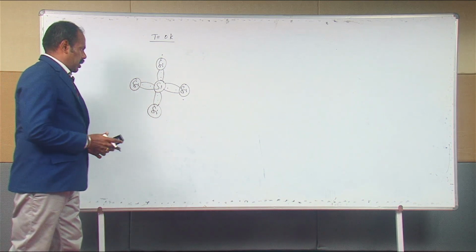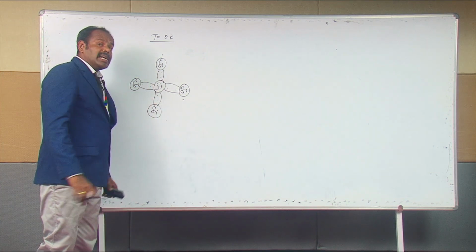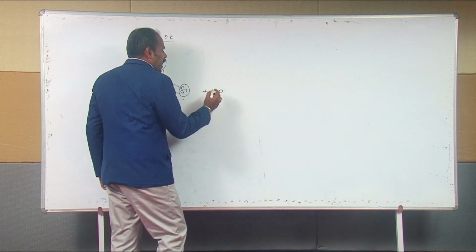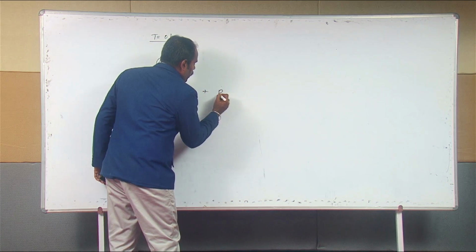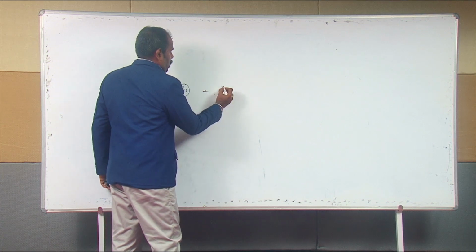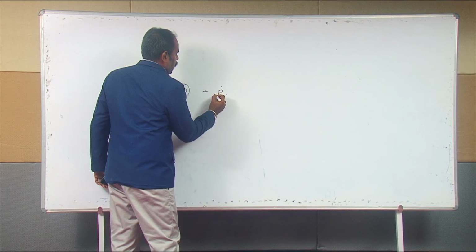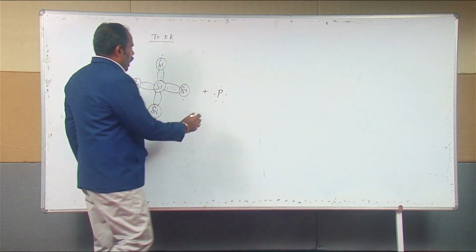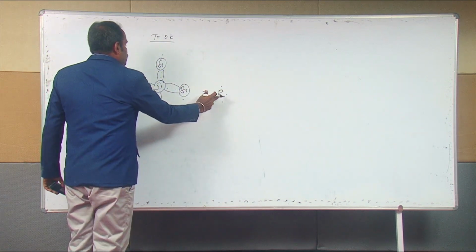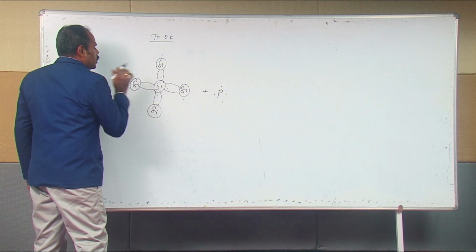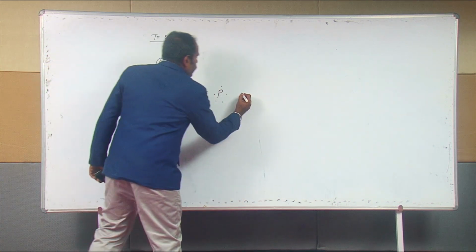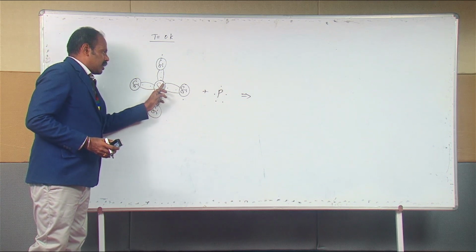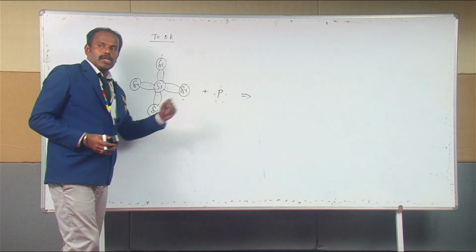So, you are going to have the network of silicon atoms like this. Now, what are we doing? We are going to add the pentavalent impurity atom into it. So, a pentavalent impurity atom like phosphorus will have 5 valence electrons: number 1, number 2, number 3, number 4 and then number 5. Right. Now, when you add this phosphorus atom into the already existing silicon network, the consequence is that one of the silicon atoms will be replaced by this phosphorus atom.